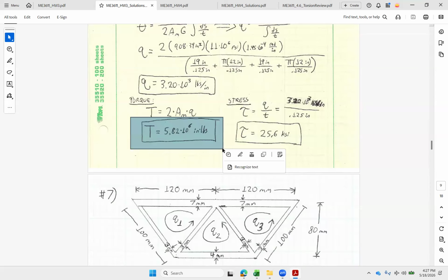The stress that we're carrying from that 3,200 pounds per inch, divide that by 1/8, so we're multiplying it by 8, and we get up to 25 KSI. It's 25,000 PSI just from the misalignment. And that's about half of the yield stress or more for that stainless steel material. This is actually a true story. Had a lot of cracking in this exhaust duct on one of the LHDs.